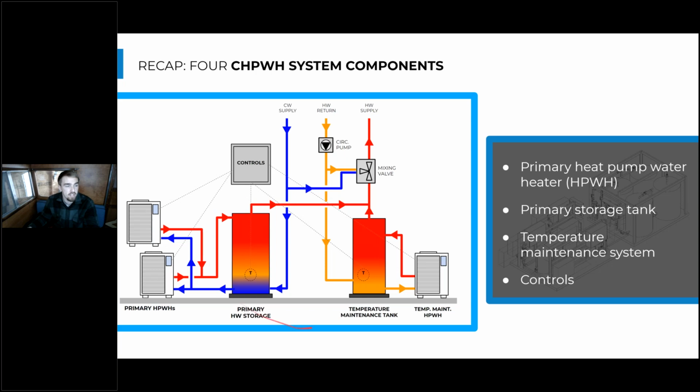You can see in this picture, we have this channel of cold water on the bottom that's allowing these heat pumps to always take in cold water and output hot water. And that flow is kind of separated from the supply flow because of the use of this storage. So the heat pumps can always see conditions they'd like to see independent of what's going on in the building.